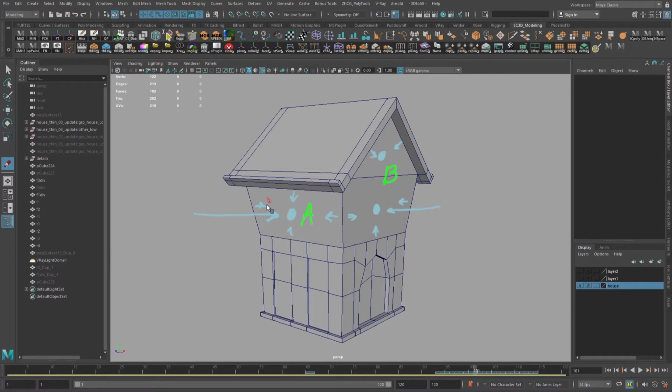Okay, so let's move to the second floor. As you can see, I will select the wall sides one by one. In this example, I will select a wall and do an extrusion offset. Right after it, I will select the face and do extrusion again. Same for wall B. I will select both faces and do an extrusion offset. I will add additional splitting lines, shape the doorway, and do extrusion for the doorway.